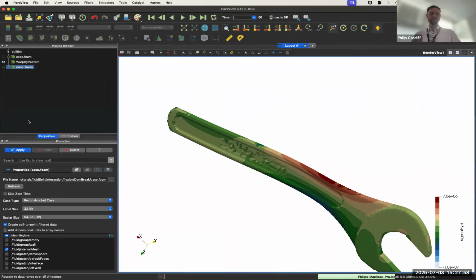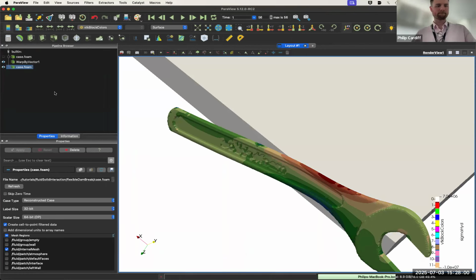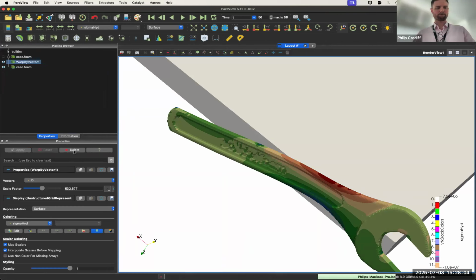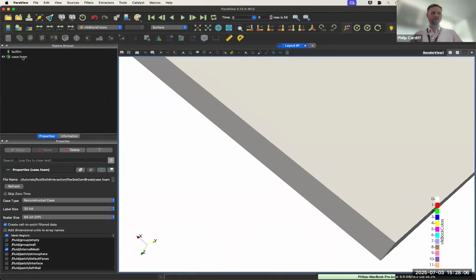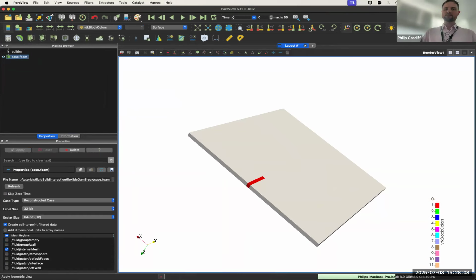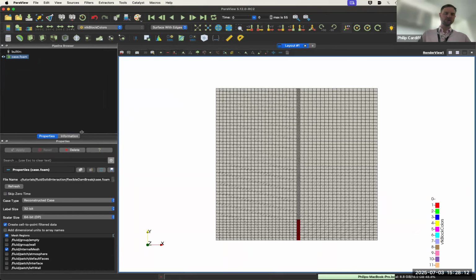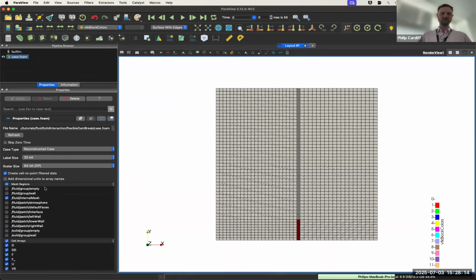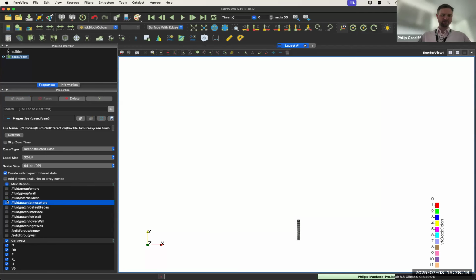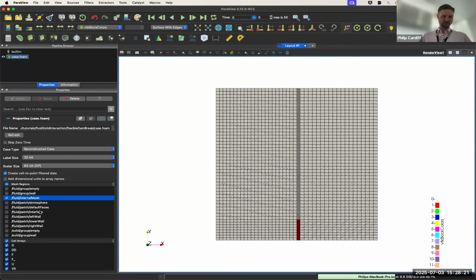So I will open this up. Perfect. Okay, set this way, and it's a 2D case, so I'll set 2D. So here's our mesh. ParaView is smart enough to recognize that it's a multi-region case, so it'll see you've got a fluid mesh. You can turn on and off the internal mesh, and it will also load the solid mesh. So it sees both of them.